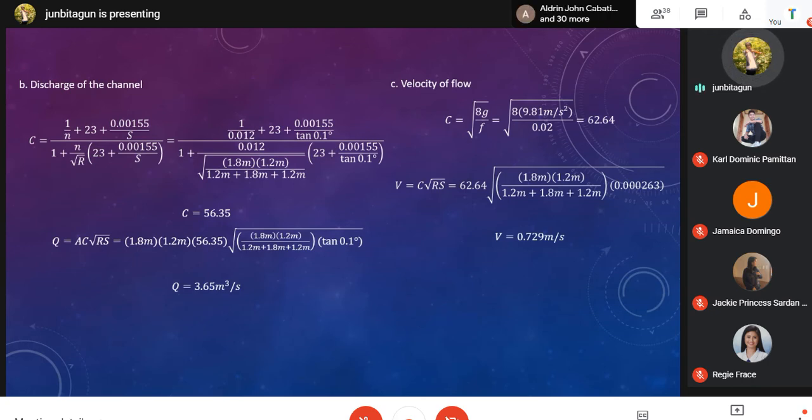So, square root of 8G over F naman. Ang ginamit dito ay yung friction factor F instead of yung N, di ba? Yung F ang ginamit natin. So, that is 8 times yung acceleration due to gravity divided by yung friction factor of 0.02. Kuha natin yung Chezy's coefficient na 62.64.